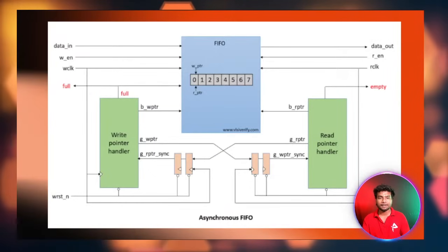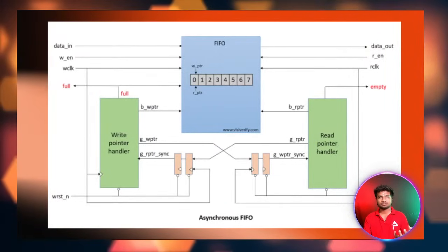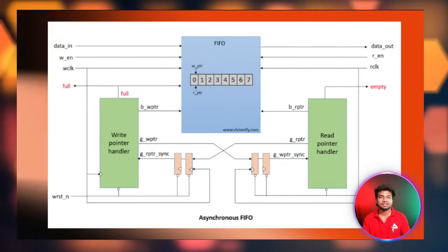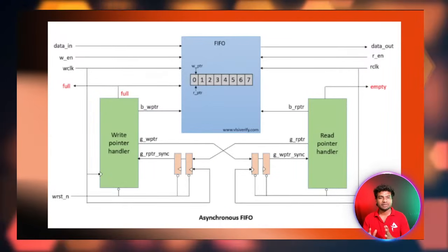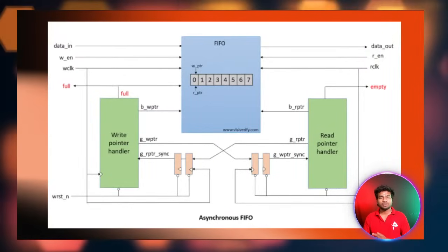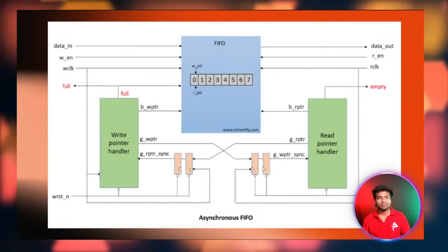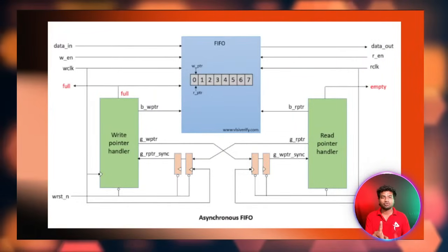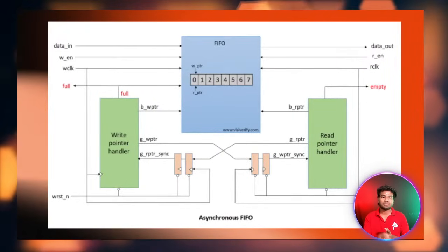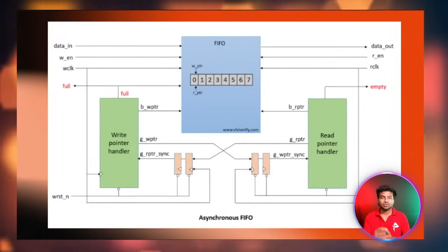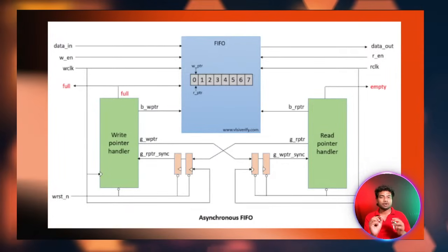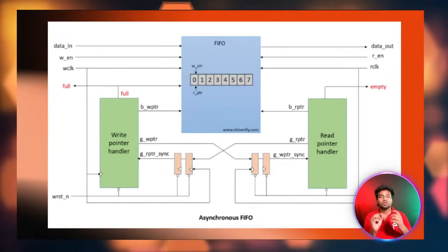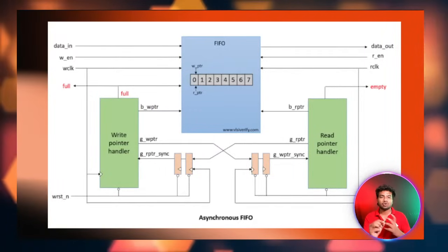So we know about setup time, hold time, and the metastability state. The signal must be stable during the setup time and also the hold time. While writing into memory and reading from the memory in a single clock cycle, in one passage, you are doing both the reading operation and the writing operation. It means you will get unknown values only.